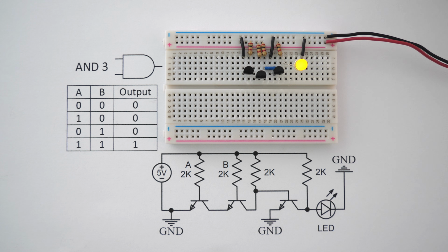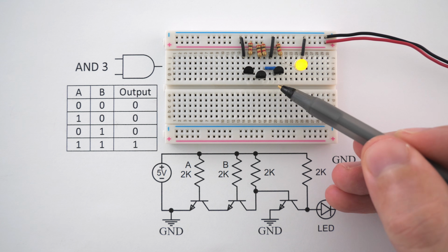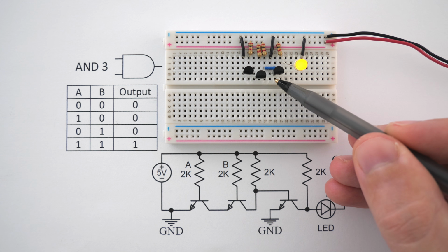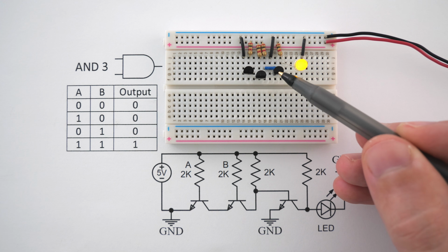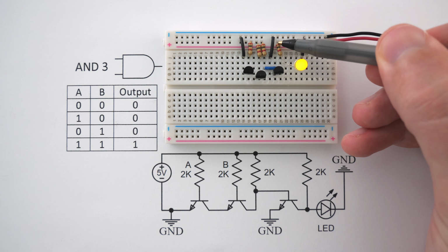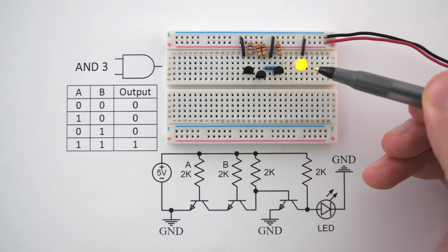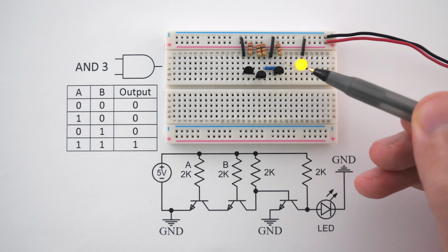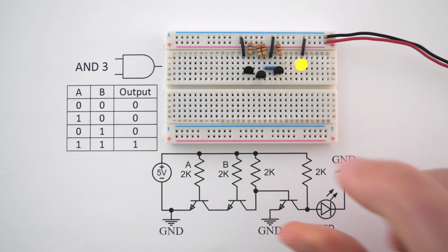And how this circuit is working is right now, all of the current from this third resistor here is flowing through the transistors and into this ground, which means none of the current is flowing from this positive 5 volt rail into the input of this third transistor. And since this third transistor is basically off, all of the current from this positive 5 volt rail is flowing across the LED and into this ground, which is why the LED is turned on.